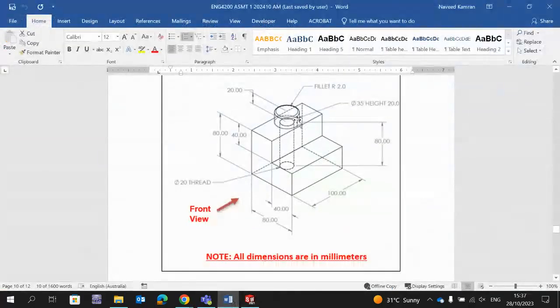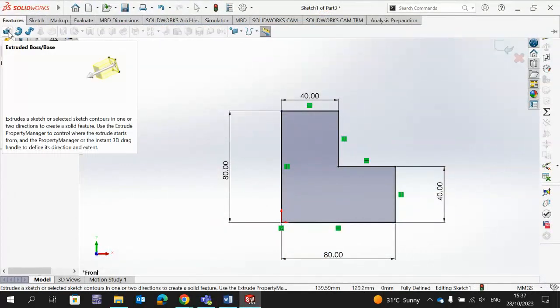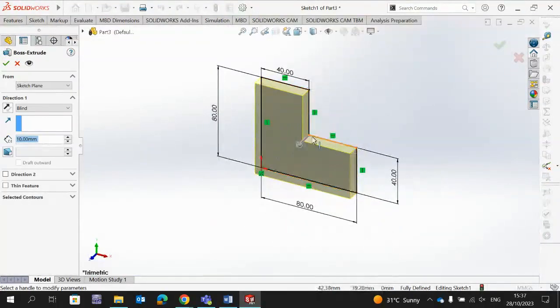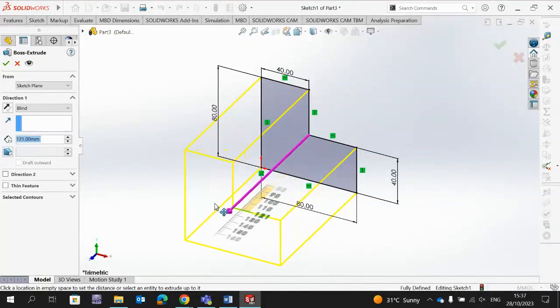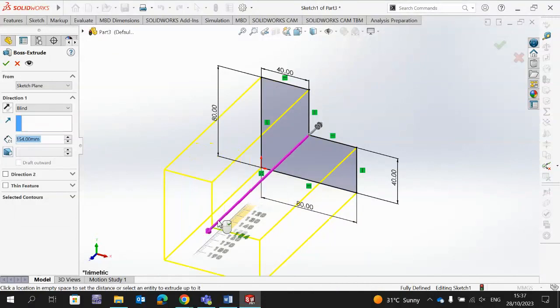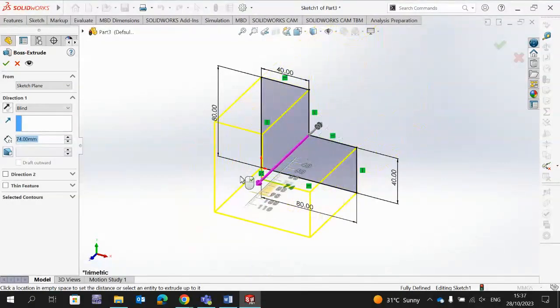Now, because it's a 3D shape, the steps are, you can say, the wide. We have drawn just this face. So we have to use a feature called extruded boss. Okay, that will give you option to make it a 3D model. So you can extend your 2D sketch into a 3D like this. You can drag this arrow, bring it forward or backward. You can make it also in the other direction, but I'm making it in this direction.